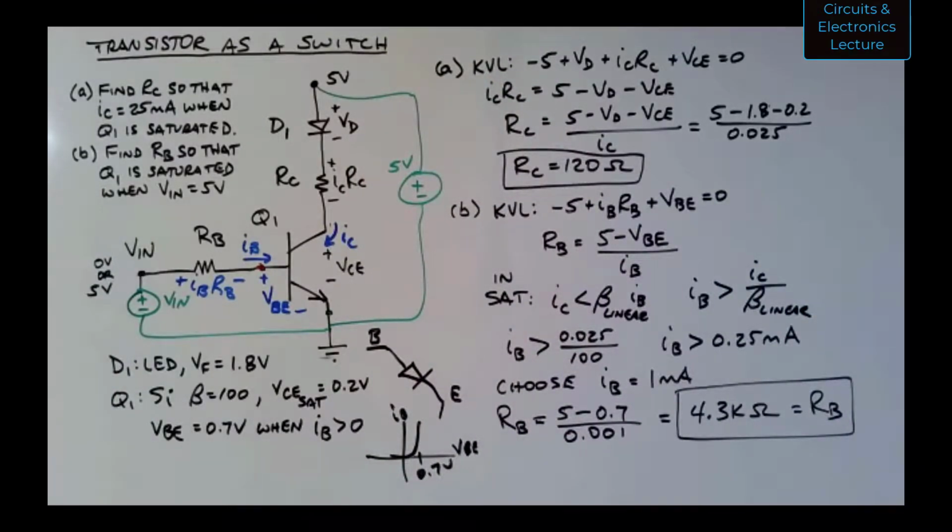That's what an amplifier is usually meant to do. It's meant to take a little voltage or a little current and multiply it up to a bigger voltage or a bigger current. Think about a microphone going into a PA system, so that you have a big voltage at a speaker from a little voltage at a microphone. You can do that with a transistor.